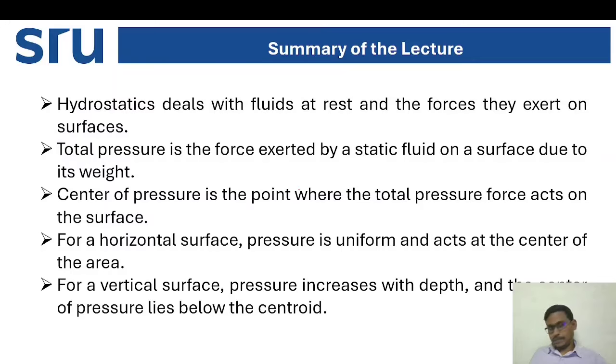Hydrostatics deals with fluids at rest and the forces they exert on surfaces. Total pressure is the force exerted by a static fluid on a surface due to its weight. Center of pressure, already we have discussed, is the point where the total pressure acts on the surface. For a horizontal surface, pressure is uniform and acts at the center of the area. For a vertical surface, pressure increases with depth and the center of pressure lies below the centroid. That is what we have seen in today's lecture.